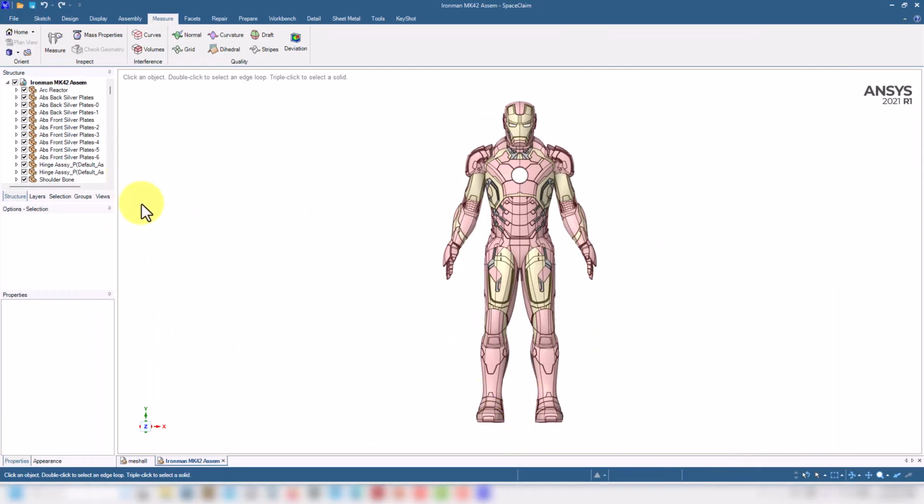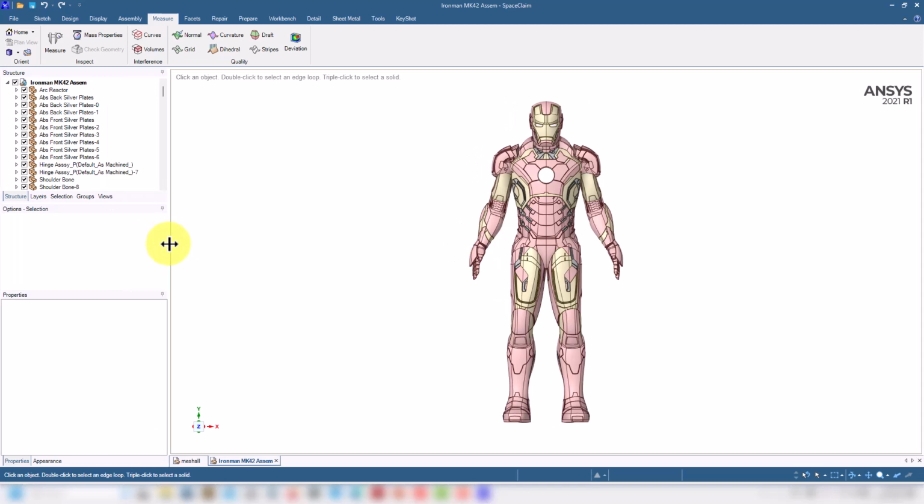So this is what we have, and let's talk a little bit about what we're getting in, because the starting point of every simulation is the geometry, okay? And then you have the mesh and so on. So whatever you get in the geometry, you're going to have in your mesh. So if your geometry is dirty and complex like in this one, that might be a problem, okay? So that is the first issue that we need to solve.